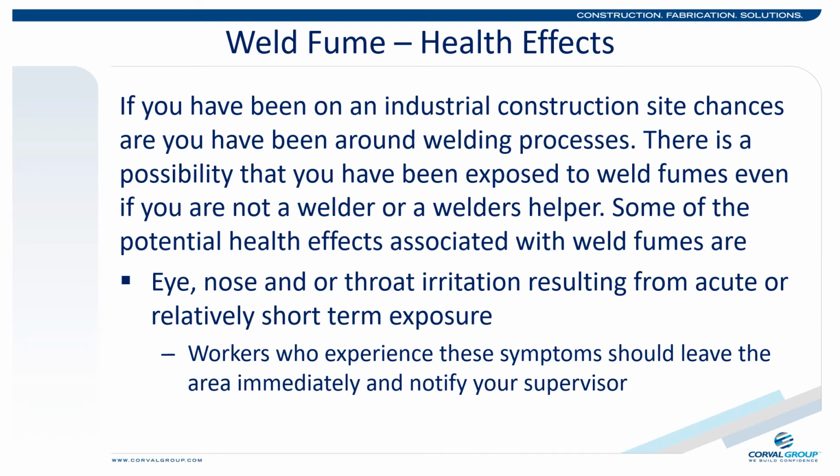The health effects of exposure to weld fumes can range from acute, short-term exposure symptoms consisting of irritation of the eyes, nose, or throat, to chronic, long-term exposures that result in impacts to our health of a more serious nature. Should you experience eye, nose, or throat irritation, leave the area and notify your supervisor immediately.